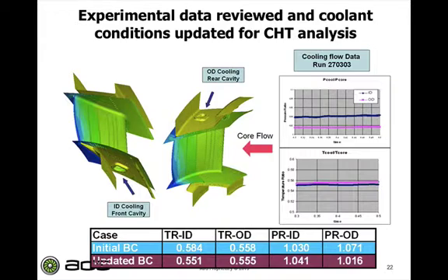Now, the way that this vane is set up, there's two supplies for the coolant. There's one that supplies this upstream ID cooling cavity, and that ID cavity supplies the leading edge shower head holes, the suction side shaped holes, and some of the pressure side shaped holes. The OD, or rear cavity, supplies the remainder of the pressure side holes, as well as these trailing edge holes.